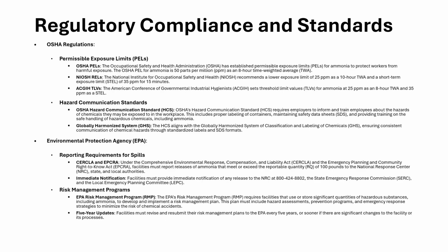Regulatory compliance and standards. OSHA regulations. Permissible exposure limits. The Occupational Safety and Health Administration, OSHA, has established permissible exposure limits, PELs, for ammonia to protect workers from harmful exposure. The OSHA PEL for ammonia is 50 parts per million as an 8-hour time-weighted average.